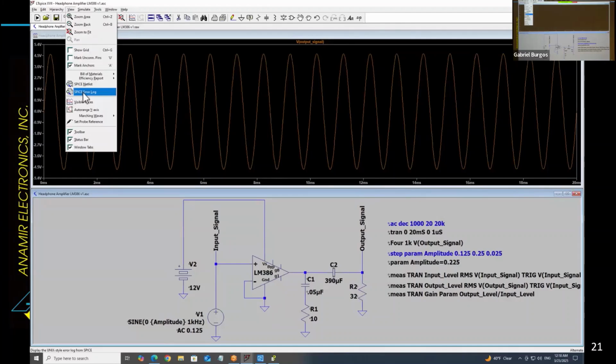That's a common mistake with Spice simulations. That's right, everything has to have a reference. If you don't have a reference, there has to be some pathway to ground somewhere, or otherwise the system can't find a solution. The machine knows it but doesn't tell you. I guess the software engineers figured you knew things like that. If you want to make an isolation, you have to add a reference, otherwise it's all going to explode.